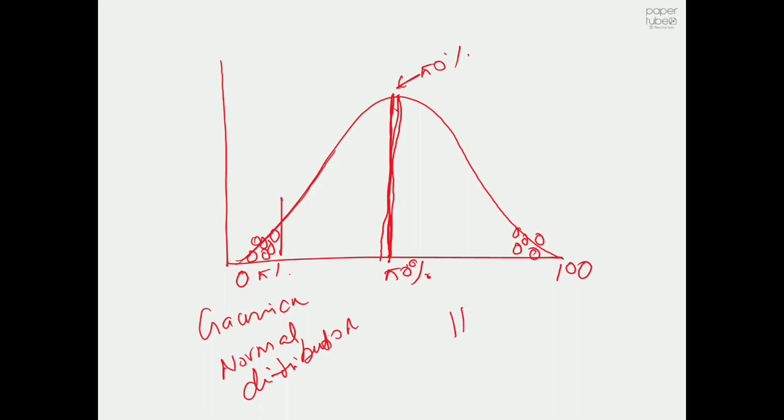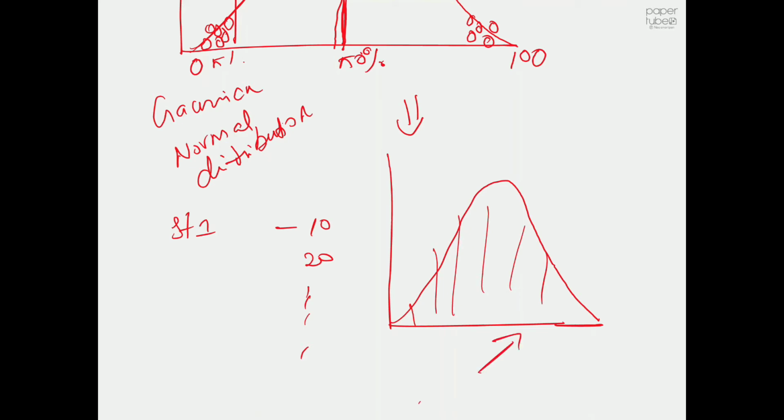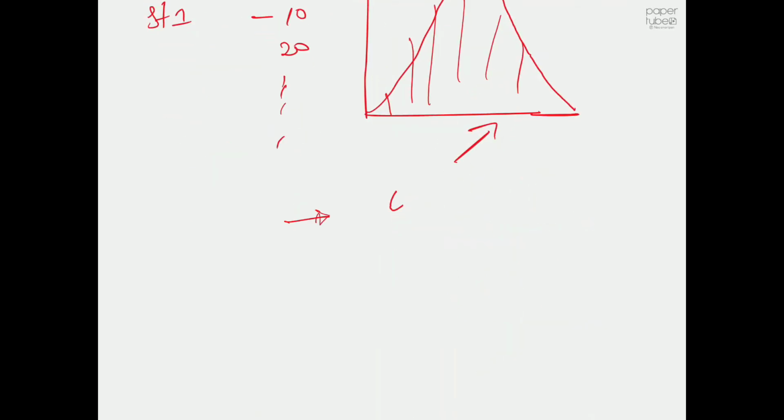And this is the same rule if you look at the experimental outcome of the column chromatography. Your experimental outcome will always be something like a Gaussian distribution, and the entire area under the curve will be equal to your concentration that goes into the reactor, something like grams per liter. The area under the curve will be some number, and that number should represent the concentration of your compound that enters your column.